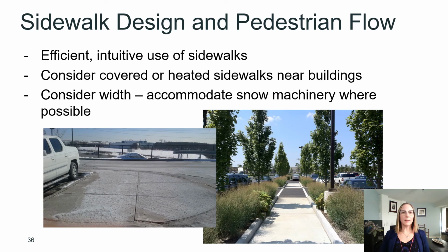So next we'll look at sidewalk design and pedestrian flow. The overarching thoughts here are just looking at the efficient, intuitive use of sidewalks, considering covered or heated sidewalks near buildings, and also considering the width. So it'd be nice to accommodate snow machinery where possible. So again, in general, what we're looking at is just trying to avoid sidewalks like the one by the truck here. That's completely unnecessary. They're all going to be salted, and it's going to be lots of it.